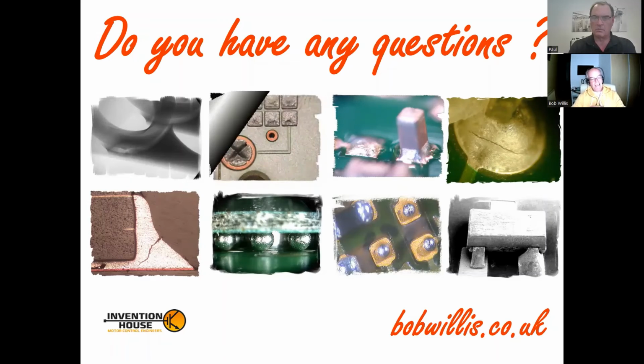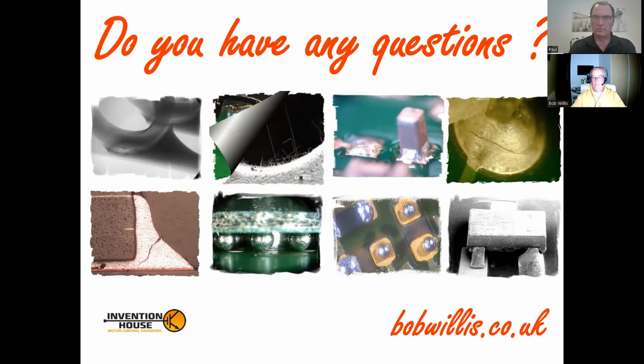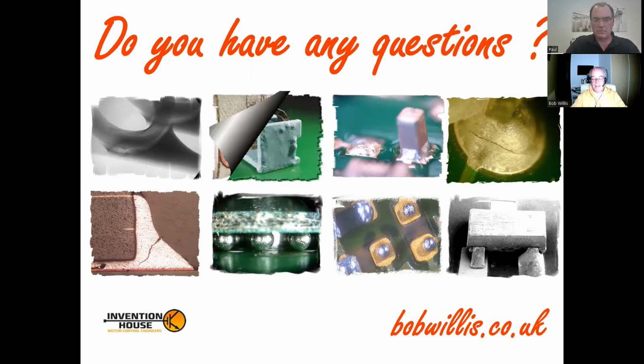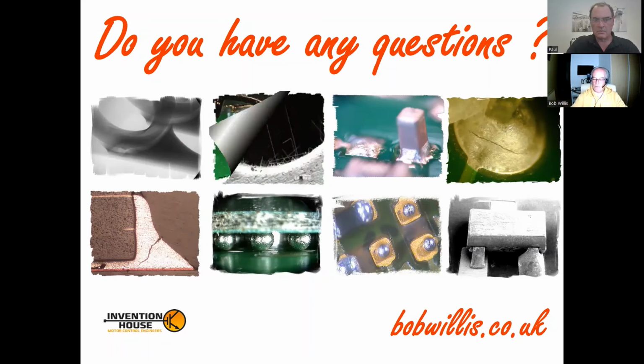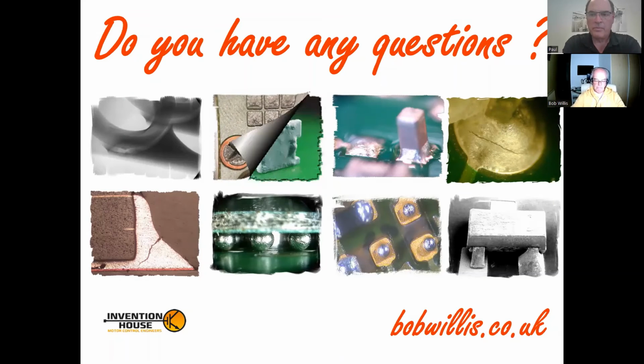So sometimes it's useful, and trivial I know, to take the sprayed board, don't get your hands too sticky, put it under a microscope and watch what happens. I'm a great believer that you can have the best machines in the world, but there's nothing like your eyesight and magnification to figure out what's going wrong or what's going right. And I'm sorry, I'm an old engineer, I do get upset when people just rely on the machines to do the job and then another machine to check the machine has done the job. Look at the real product. That's how you learn how to solve problems in manufacture.